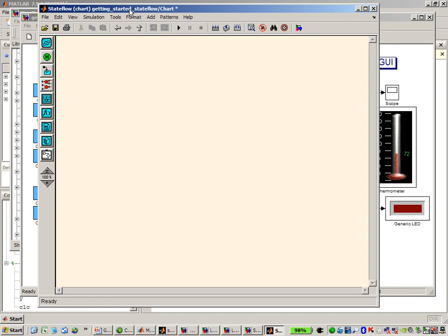And first thing we need to do is represent the main states of our system. So what are the top level states? All right, so this is usually how I build the Stateflow charts, as I go from the top level and work down. All right, so I know that the top level states of this device, it'll either be on or off. All right, so I'll represent those two modes or states with a state. So there's the state object. So we have device off.